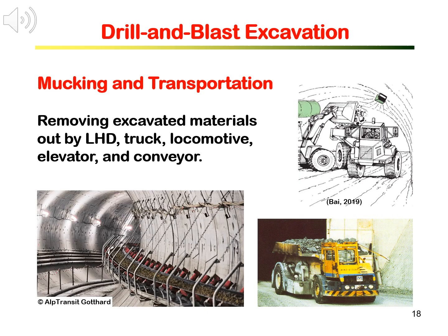With ventilation and scaling done, the excavation area is safe for the mucking crew to come to remove and transport the excavated broken rocks and fragments out by LHD, trucks, locomotives, elevators, and conveyors.